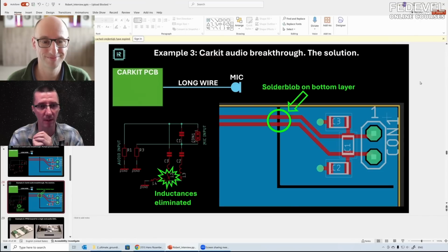The second example was with a failing ESD test. It was not like this. They actually recommended placing a ferrite bead between these two ground planes, and it always discharged through the chip, and it damaged the chip. Of course. The solution was to use a 0 ohm resistor, but the best would be just don't separate the grounds, just make a solid ground plane.